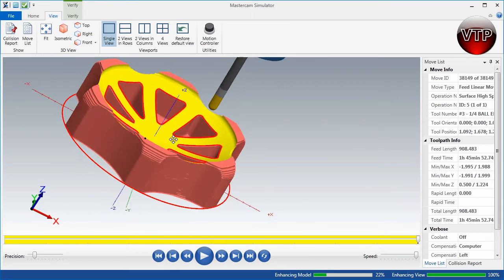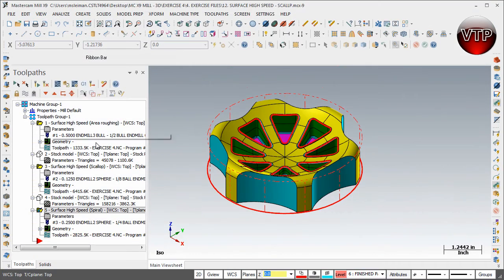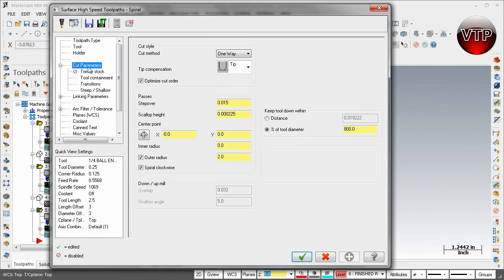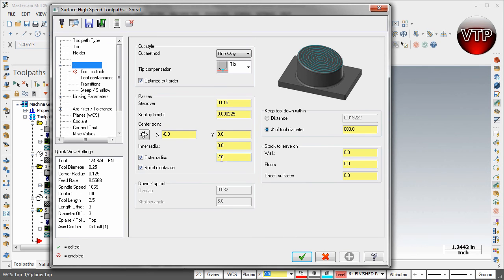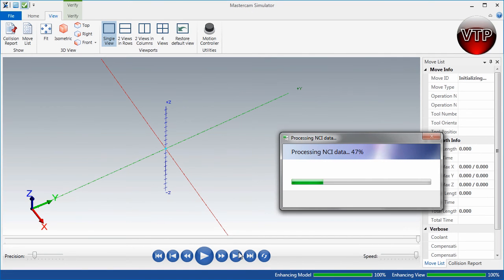Now I'll show you the same thing, but increasing the radius. What will my tool do when I increase the radius? So go back to my part, click on parameters. Okay, click on cut parameters over here. I'm going to change my radius to, let's go ahead and just change it to 3.0. Select apply, and I'm going to regenerate dirty operation in my verify simulation,